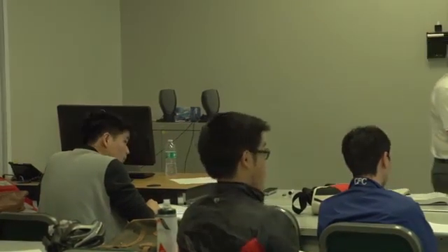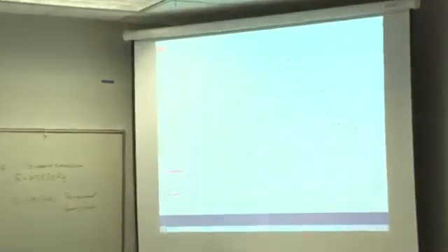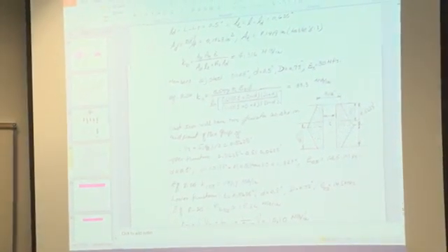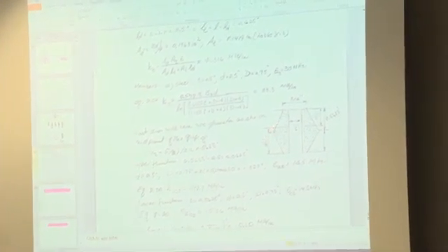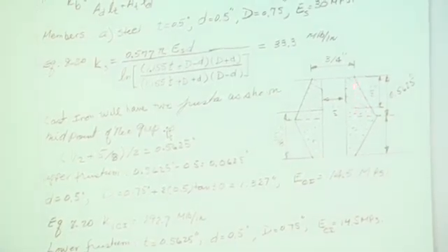This is the total grip length. That's capital D for the top frusta, capital D for the bottom frusta. These are our 2 load distribution lines at 30 degrees. And notice that the top part is steel, so you have to calculate a K for that.